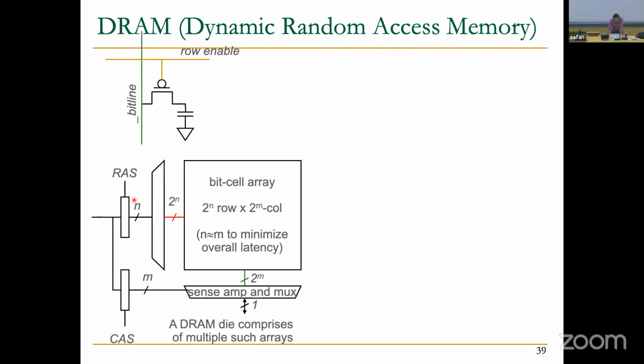So basically in DRAM you have what you call a row access strobe or RAS. You will provide your row address in one cycle, and you will store that here in, let's say, a latch or a register, and in another cycle, using the same signals, you need to provide a column address. So first you provide your row address, you bring data to the row buffer, and then in a consecutive cycle or some cycles later, you will provide which column you want the data from.